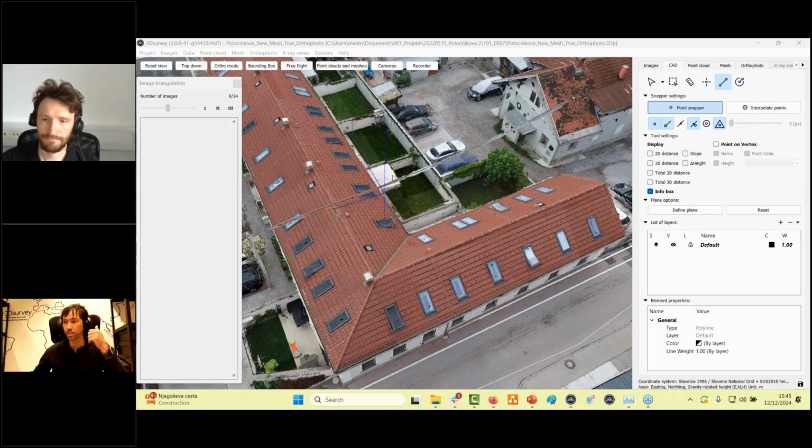The first issue is your drone GNSS or drone GPS. It's always great to have at least one GCP point to align this, because if you fly without GCP points, it can be 10 to 30 centimeters off. Another one is that sometimes the camera parameters are not calculated perfectly. What could help with this when you fly a single grid mission is to use the option in DJI, optimize elevation, something like that is there, and this can improve it. Okay, thank you, Marco.